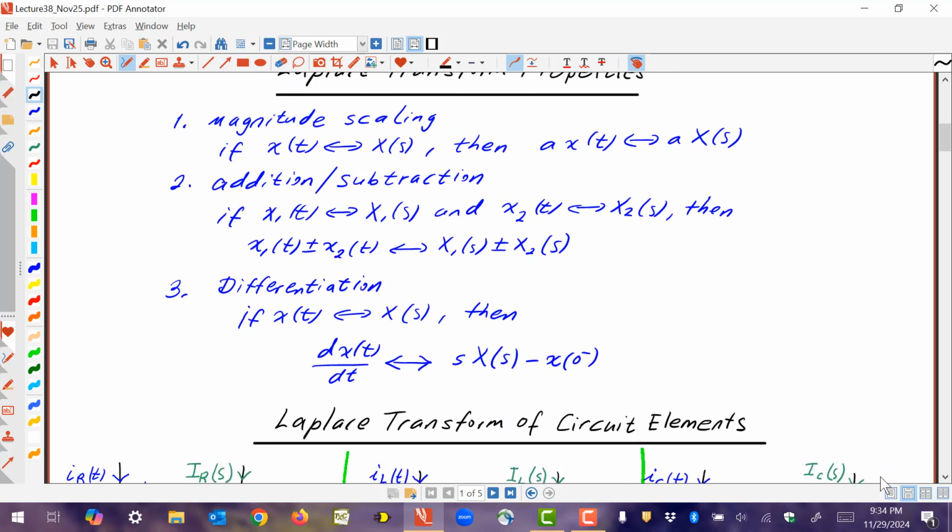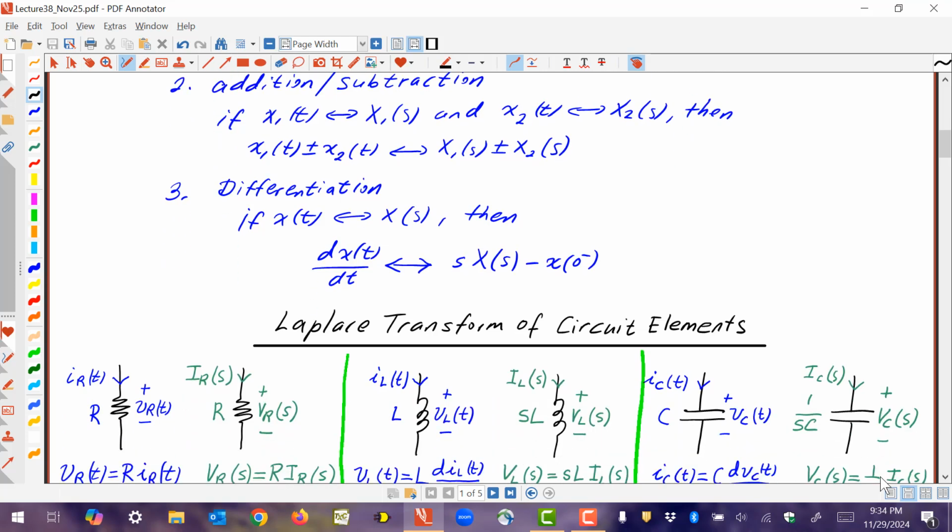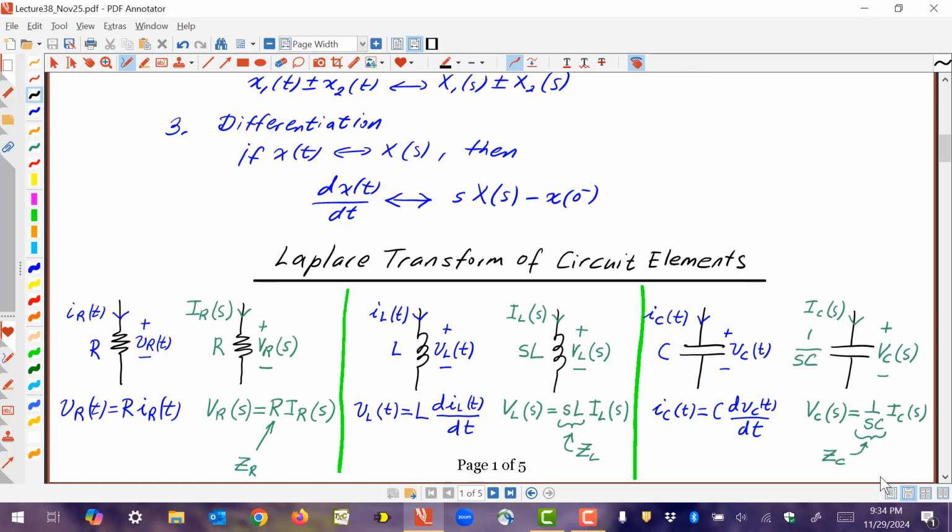Okay, so let's start with some other fundamentals before we jump into examples. The fundamental is that each circuit element can be replaced by its Laplace transform equivalent when we solve problems. So instead of finding the differential equations and taking the Laplace transform of the differential equation, we can just take the Laplace transform equivalent of the circuit, and then the circuit becomes an impedance circuit, like a phasor circuit with impedances in ohms, and it's basically solving a DC circuit.